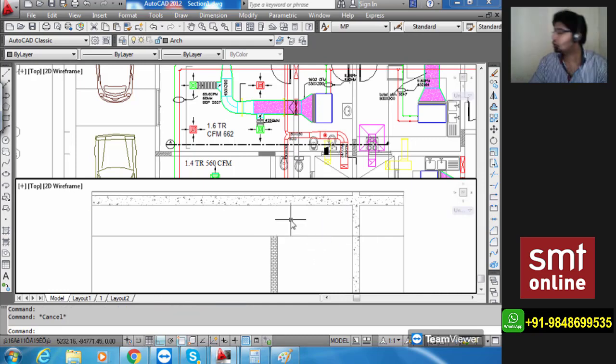Now also inside the service area, what all things are going to apply from above to below? What is the first service, what is the second service, and so on. The first service would be firefighting, then you have plumbing, then you have the electrical lighting fixtures, and lastly you have the AHU, the HVAC that is near to the false ceiling, right? So with plumbing, firefighting and electrical, I'm distributing totally 2 feet for them. Alright, 2 feet, or maybe I'll keep 1.5 feet for them. The remaining 1.5 feet is left for HVAC drawing.